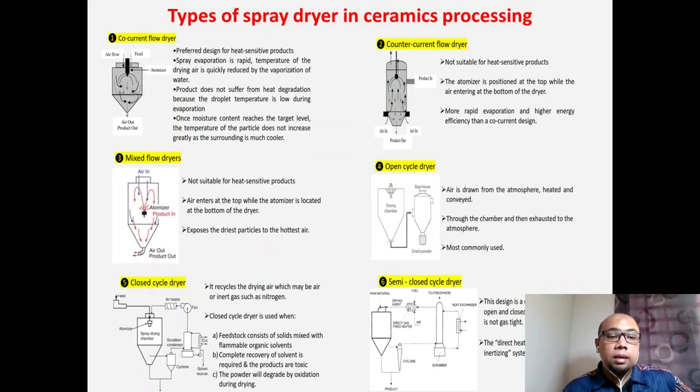From this type of slurry, you will channel the output, or charge the slurry, into the spray dryer, and then the slurry goes through inside the spray dryer, and they will heat it at a gradient temperature inside the spray dryer, and then at the end you will get the ceramic powder as granular shapes. Normally we produce something like pebbles, something like gully shape of ceramic powder.